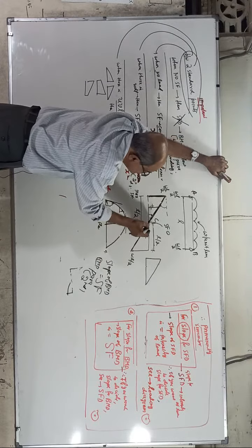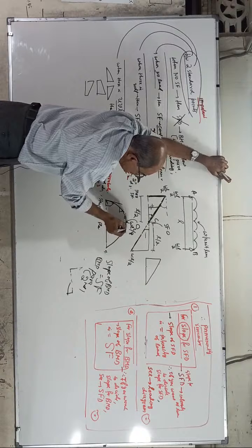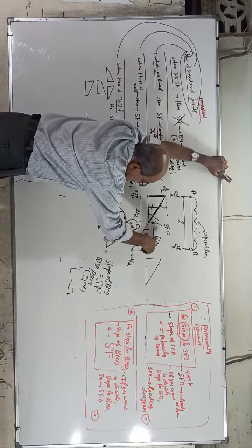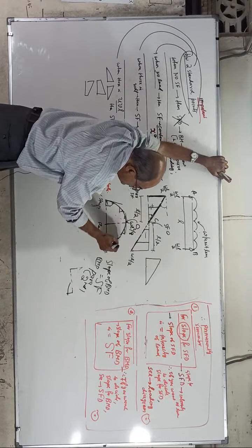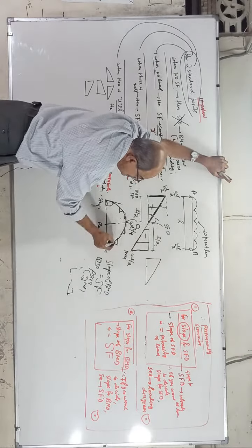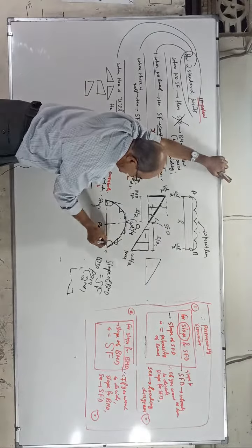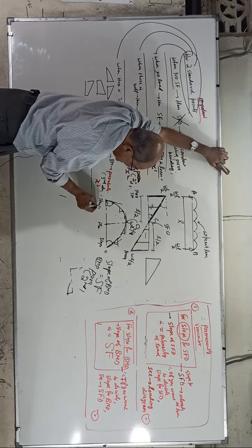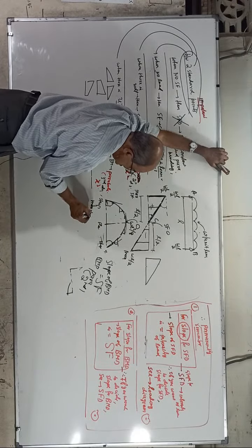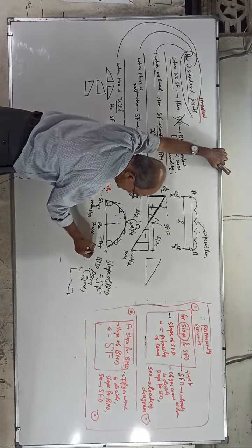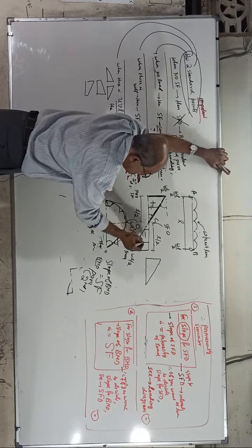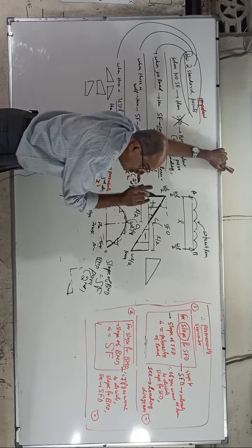Again on that side, somewhere here, shear force increased on the negative side, slope increased, but opposite. As you go here, shear force further increased on the negative side, slope further increases. When you come here, shear force is once again maximum, negative maximum. So slope is steep here, once again steep here: maximum slope, zero slope, maximum slope. But here shear force is positive, slope came anti-clockwise. Here shear force is negative, slope came clockwise.